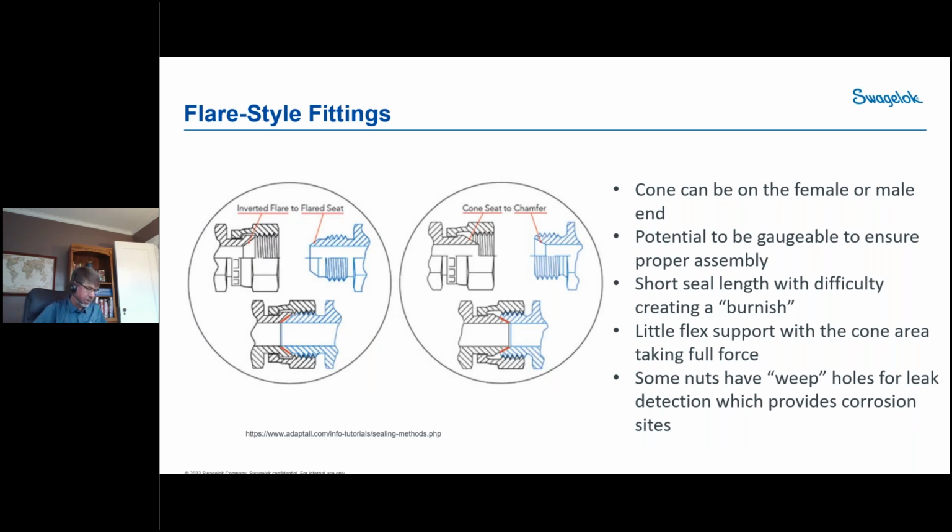So people said, let's get rid of the O-ring. And we designed this flare style fitting, where there are two metal pieces coming together at an angle. And that angle is intended to drive the force into those mating surfaces, creating a burnishing effect, but still maintaining the gaugeability of the fitting design. So it still maintains gaugeability, but eliminates the possibility for permeation.